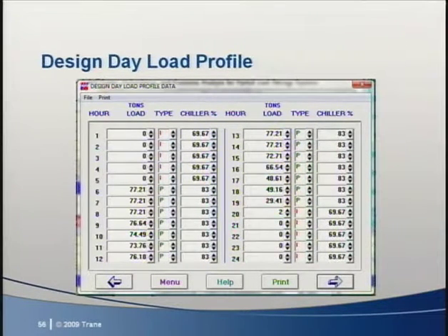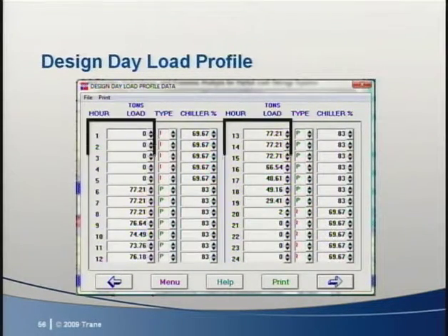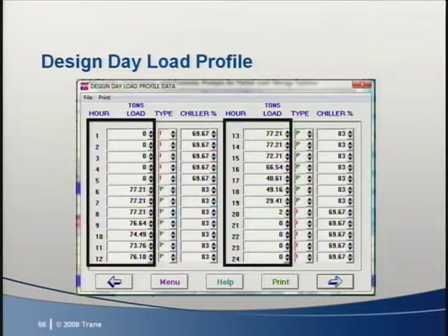Over the weekend and nights, the BAS system allows the building temperature to drift up. The next day, the temperature is ramped down by the automation controls in order to have the building reach set point temperature by class time. This causes the high Monday morning startup loads of our peak August day.